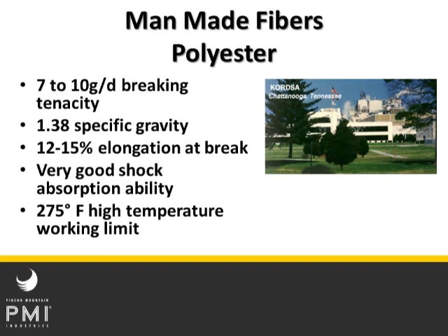But as you can see, the strength range, the grams per denier, it's about the same as nylon. It has an even greater specific gravity, so it's going to sink to the bottom even faster. It has much less elongation at break. It's 12 to 15%, where the nylon was half again that, I guess. It has, instead of excellent, what they call very good shock absorption ability. It means that it isn't going to break, but it really doesn't elongate very much. 275 degree high temperature working limit on polyester.